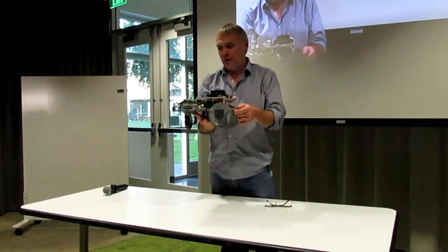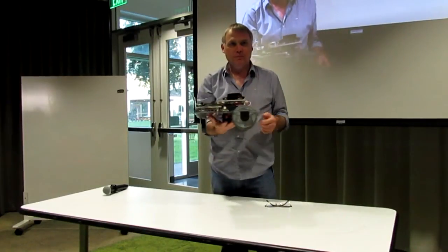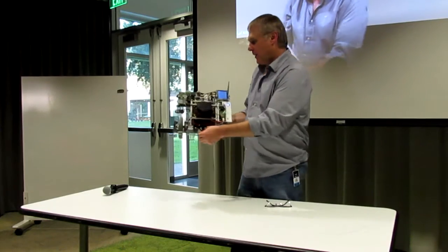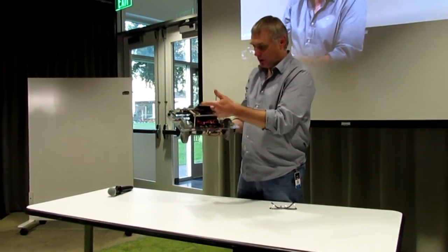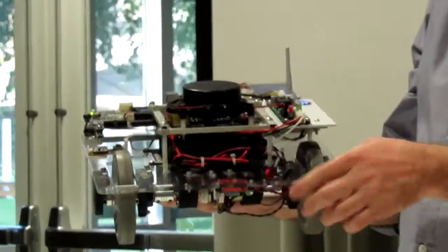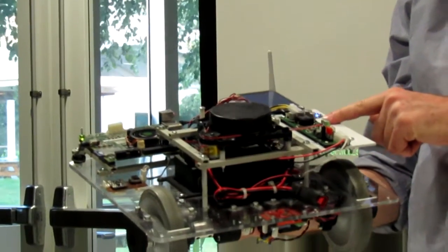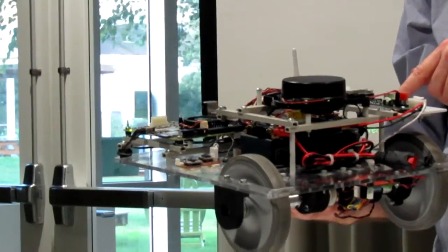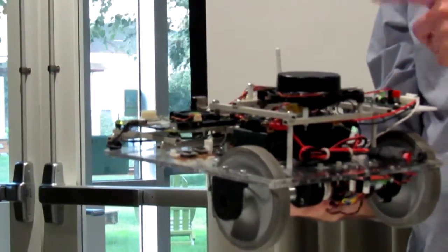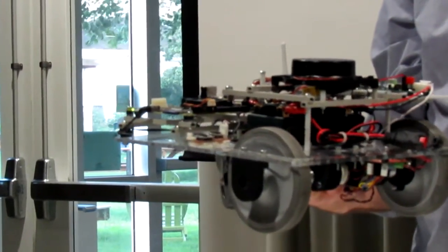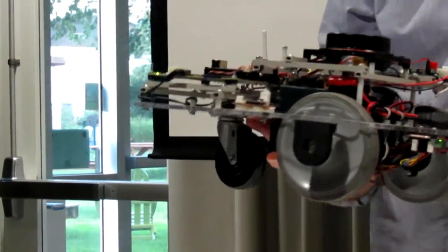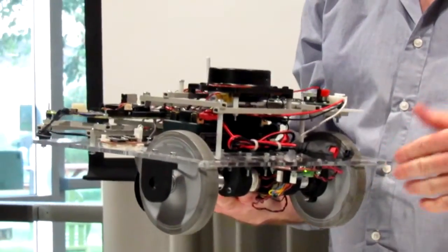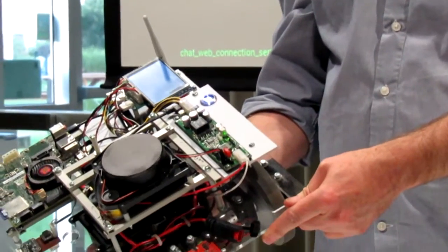So now at home, it will actually do mapping and navigation. It's had some fairly major upgrades recently. The LiDAR is one of them. I put in a new power supply board, discovered this great little regulator. It's a buck boost, so it'll take from like 8 to 25 volts in and give you normally 12, but you can even program it to 5 to 24 volts out, so the battery can go above or below it, and it continues to give you power.